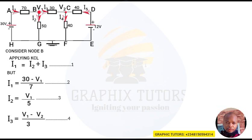Is that okay? Now, we will substitute I1, I2, and I3 into equation 1 above. Now, if you look at my equation 1, the first one here is I1. So what is my I1? My I1 is 30 minus V1 over 7, equals to, what is my I2? My I2 is V1 all over 5. And my I3 is given as V1 minus V2 over 3.